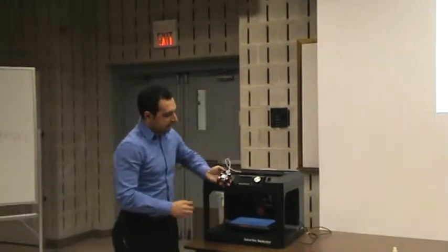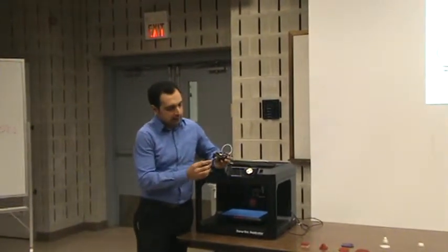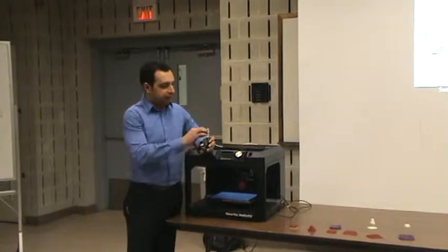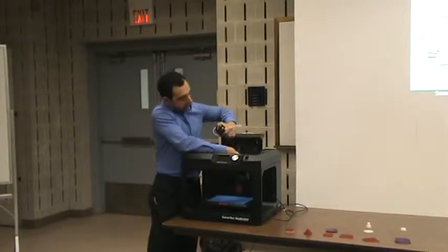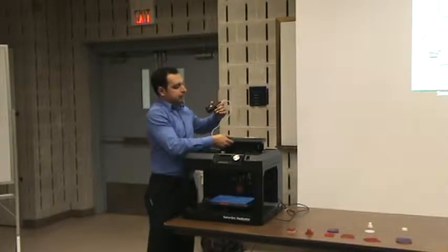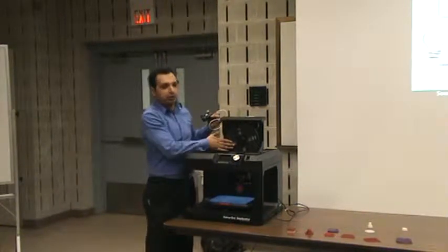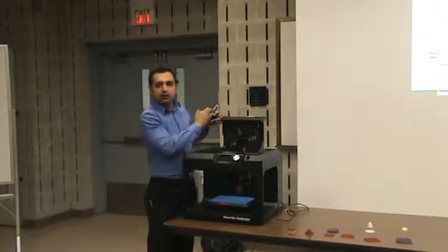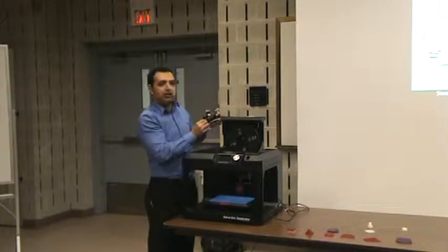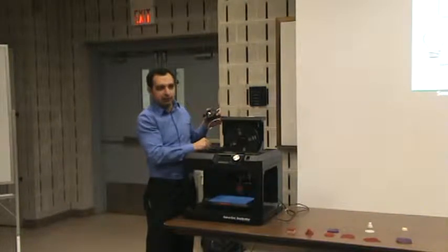So this is basically the extruder, and you can see that this tip will melt out the filament that is going through it. You have the filament in here. The filament is mounted on a spool right here, and it is pushed. You have two miniature motors that will push the filament, and the nozzle is heated to close to 180 degrees.